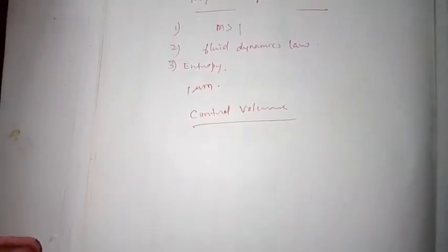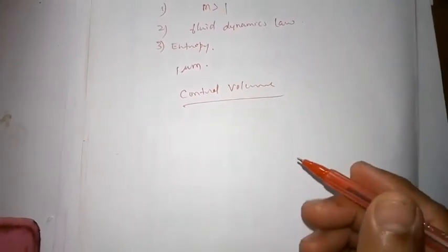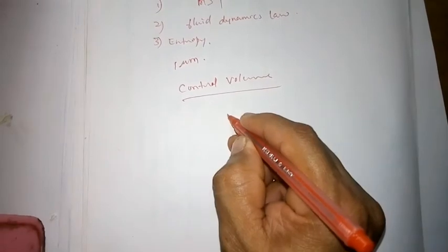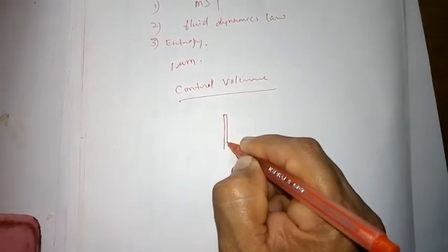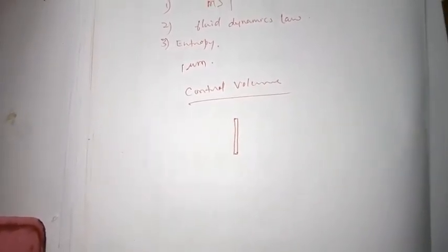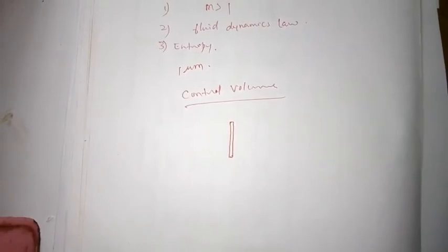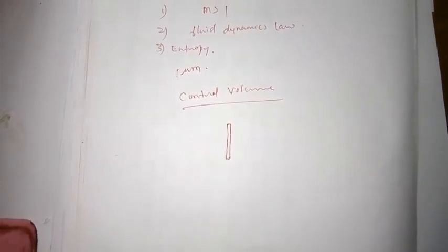Control volume is a model on the basis of which shock waves are analyzed. It is an imaginary thin envelope that surrounds the shock front, within which there is a sharp increase in pressure, temperature and density in the compressed medium. Consider two regions, pre and post.